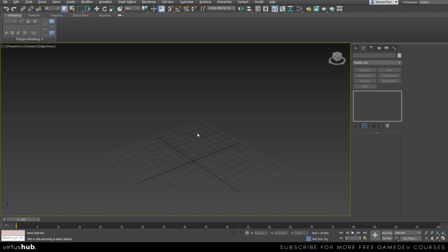The other thing that I like to do is take care of my unit measurements first, and this goes to anyone who's using any 3D program, because the assets that we want to make for game design will go into a game engine. A game engine has already pre-established units, unless you know how to mess with that, which requires some programming, but the default's usually the metric system. So whichever 3D software that you're using, make sure that your units are on the metric system.